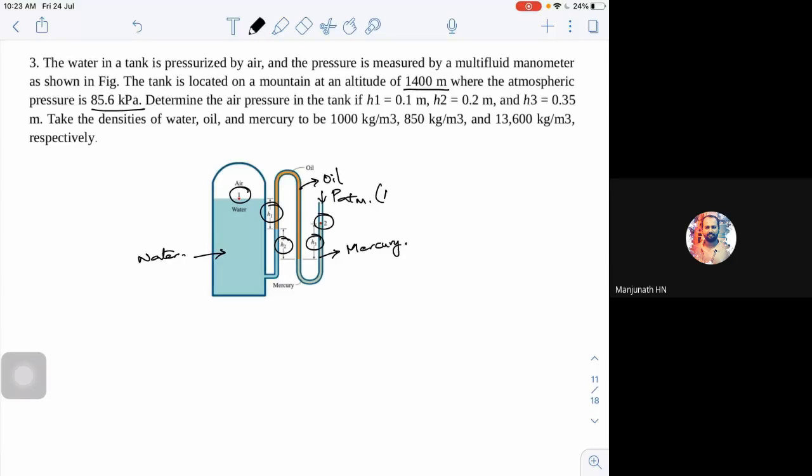Okay. So a lot of questions will be in your mind. What will happen? Say the same manometer, for this particular height, what value is it going to give in Bangalore? Now suppose I take the same manometer to a hill station like Nandi Hills or Tirupati, will the numbers change? Yes, it's going to change, because altitude is one particular parameter, and based upon that my pressure is going to change.